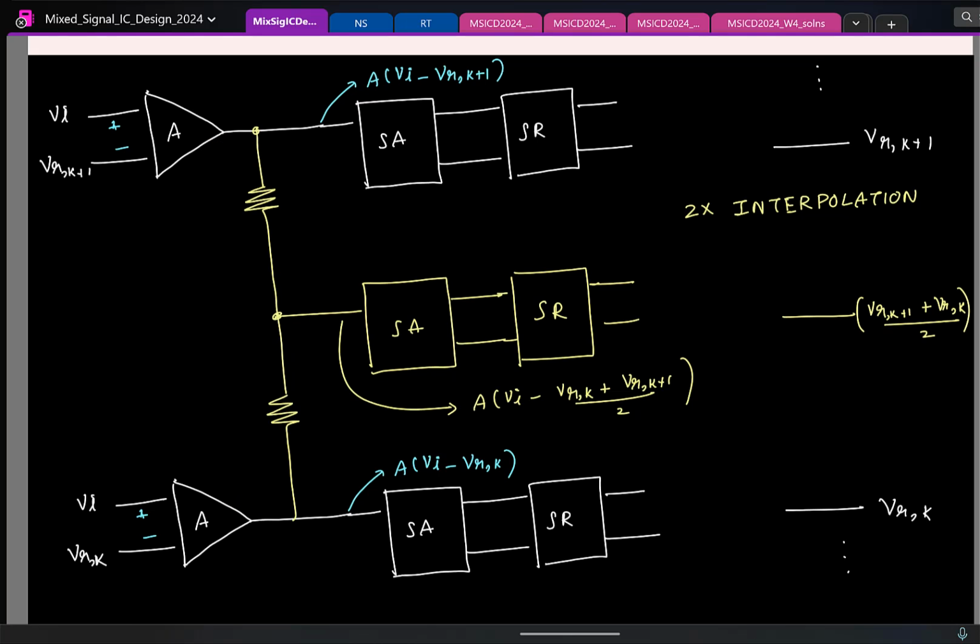See, this entire premise is based on the assumption that you get this voltage here and this voltage here. Of course, the input voltage is the same for both the comparators, both the preamplifiers here, fine. The reference voltages you might have generated, that is also fine. But what is one thing that can change? Yeah, gain, right? I assume that the gain for the two preamplifiers is the same.